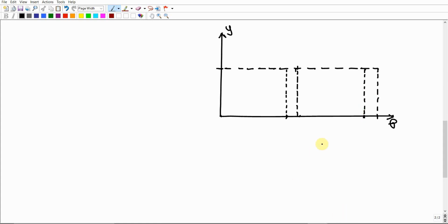Make sense? So these are the 4 periods that we already discussed here. We have the rise for 5 centimeters, the dwell, the return for 5 centimeters, and another dwell, in the beta direction. So this is like beta 1, beta 2, beta 3, beta 4, as we already discussed up there. Make sense? Then your objective is just to start generating the first type of motion, which is the simple harmonic motion within the rise period, following the same procedure that we explained in the previous video for generating the simple harmonic motion.